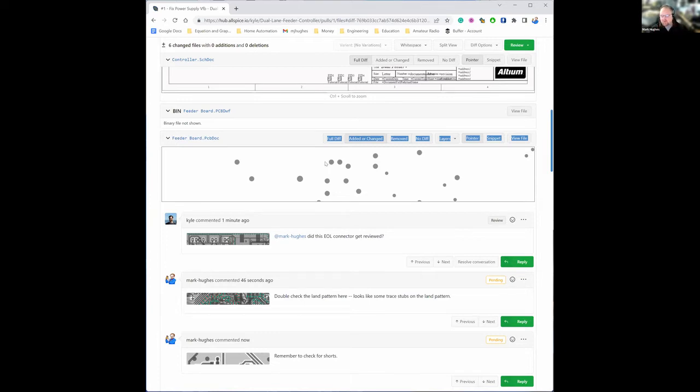If you put the holes too close together, the drill can actually break through the PCB, right? The drills wander ever so slightly. There's going to be less force coming from the side of the drill hole that has a hole right next to it than on the other side. So that can cause the drill to wander into that hole. Manufacturers usually require some minimum amount of board between two holes. That can vary anywhere from an eighth of an inch down to 0.1 inches. It just depends on what you're doing and what machines they're using.